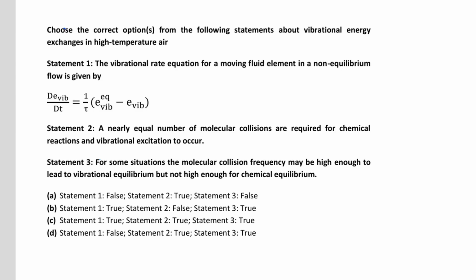Now we will see the next problem. Choose the correct option or options from the following statements about vibrational energy exchanges in high temperature air. Statement 1. The vibrational rate equation for a moving fluid element in a non-equilibrium flow is given by d E vibrational upon dt equal to 1 by tau times E vibrational equilibrium minus E vibrational.